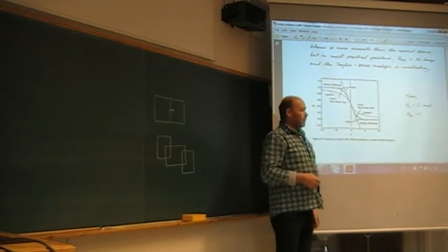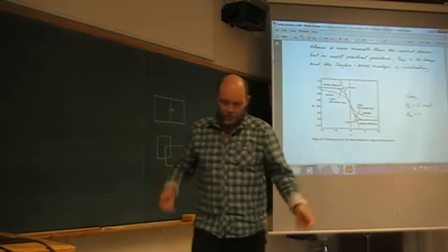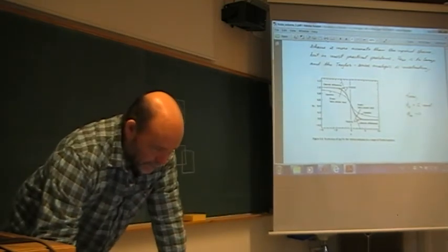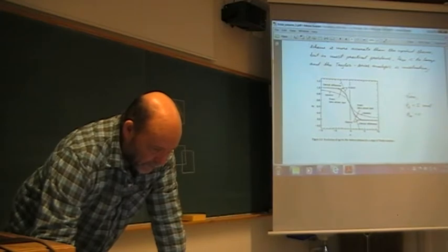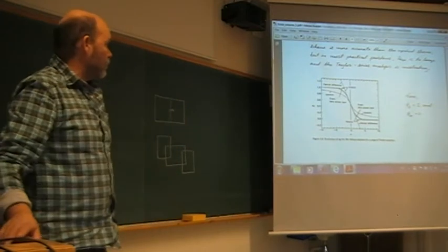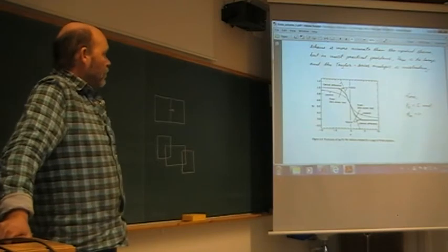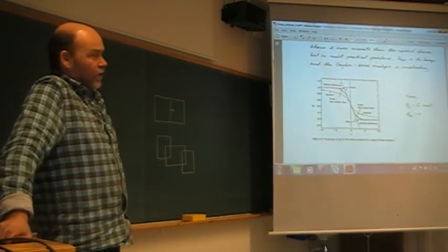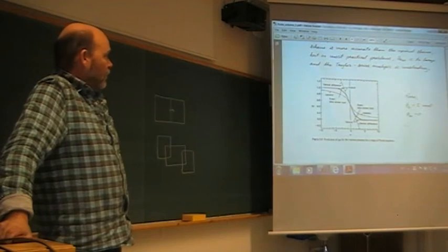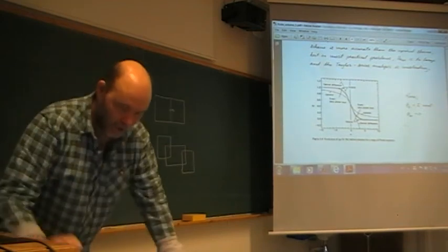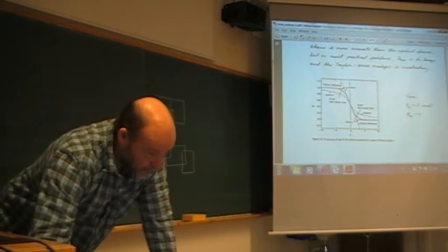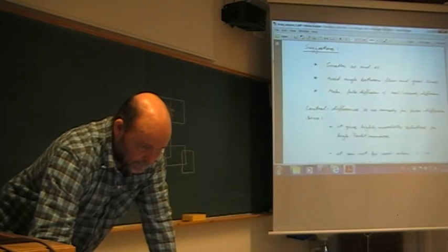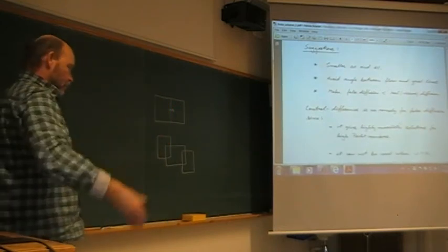And unfortunately, if you can't use it, the Reynolds number is too big, then you should really know what you are doing, using quite advanced, I would suggest, upwind schemes, like QUICK, MUSCL. You have several of these advanced upwind schemes. First order upwind should never be used, except maybe for creating an initial field or something.